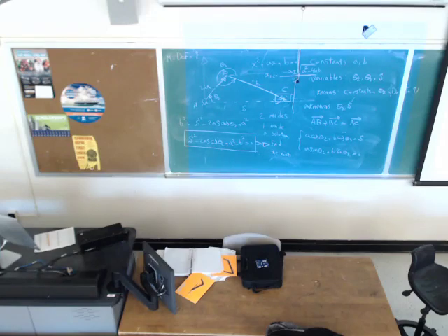You use your calculator or MATLAB to find theta 3. Your calculator is going to give you one angle. But this is not the only response, it can also be negative theta 3. So this one or this one. We don't know which one is the correct answer. Back to this equation, sine of theta 3 equals A sine of theta 2 over B, where A is given, B is given, theta 2 is given.